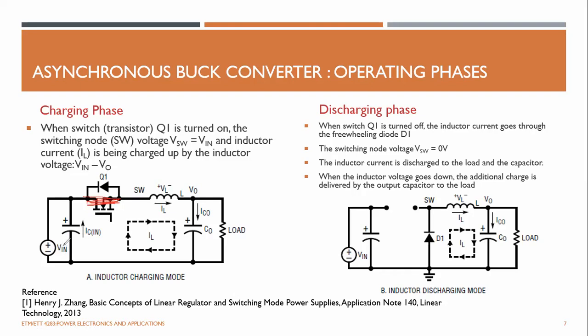So now you can see this battery current can go through this inductor, some part of the current can go through the capacitor, and other current can go through this load and circulate back here, right? So this is the charging phase, and we have this switching node, known as SW, which is very important when you're designing your controller, because the switch node is a very important thing for dealing with the EMI, right? It's a very fast changing voltage point.